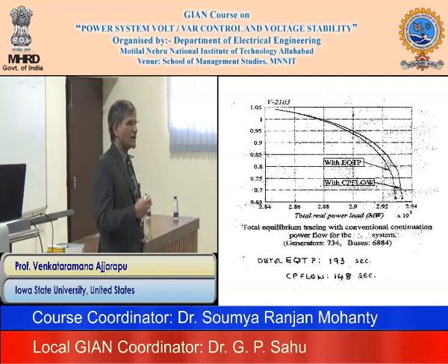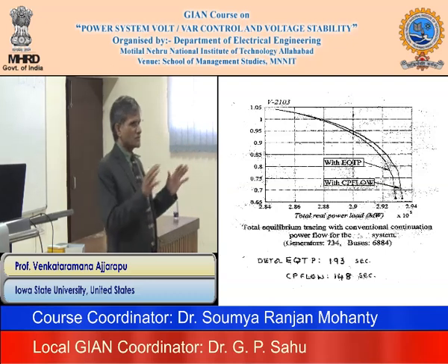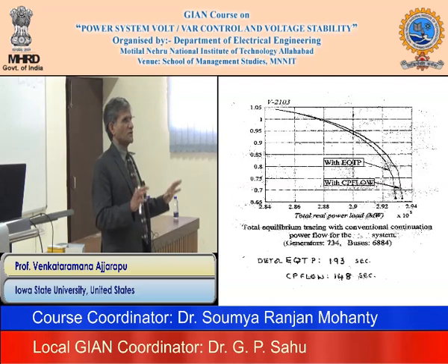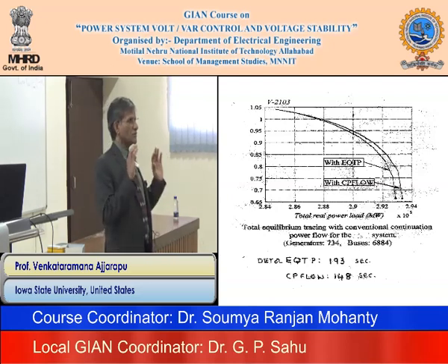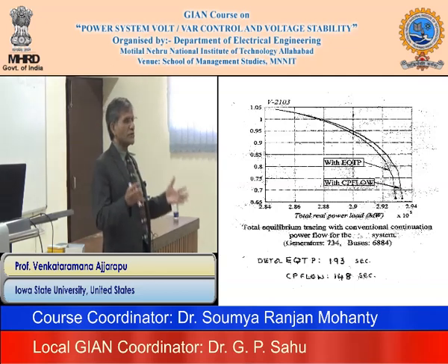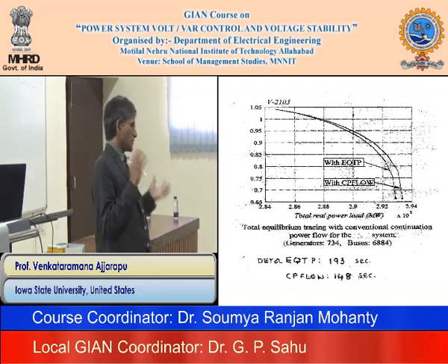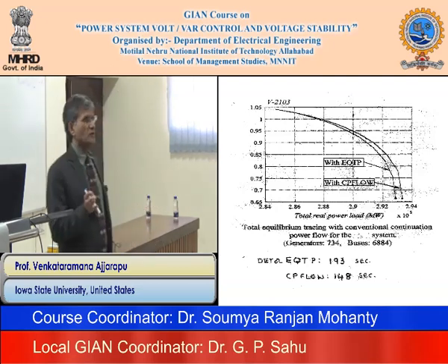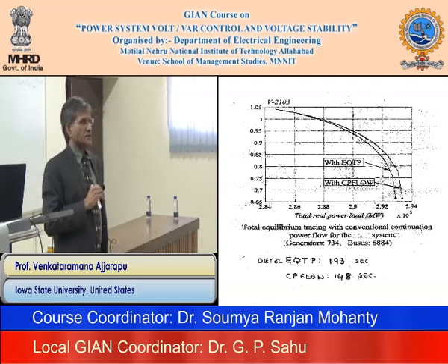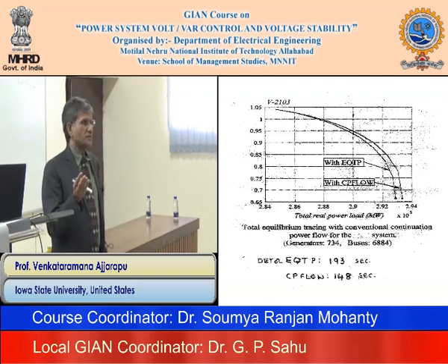But power flow, we do that because you do all these contingency analyses, right? For the moment, you don't worry about which generator is taking the losses and so on. To get a convergent solution, you assume some generators are slack bus and do the contingency analysis and make sure the system is secure or not. Once I know that, then I don't need to worry about it. You don't use the power flow to distribute the generation to the generators. The governor's job is making sure that load is balanced with respect to generation.